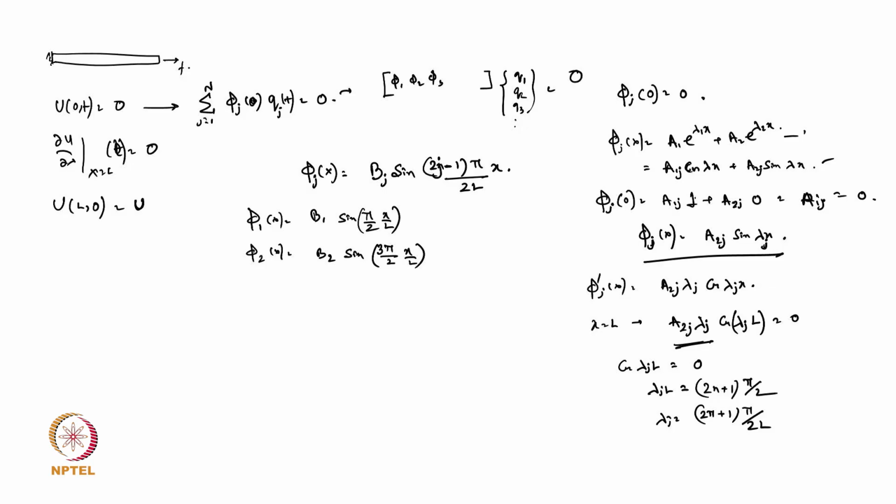But once you come to the spectral or some sort of mixed type of method, there you are designing that, okay, this should be my function, this should be the function for that particular boundary condition, so that my solutions can come much easier. So here is the difference with the finite element. And due to that beauty of the finite element, it does not depend on the boundary condition, therefore it becomes general. You don't need to think at all about what boundary conditions you are using.